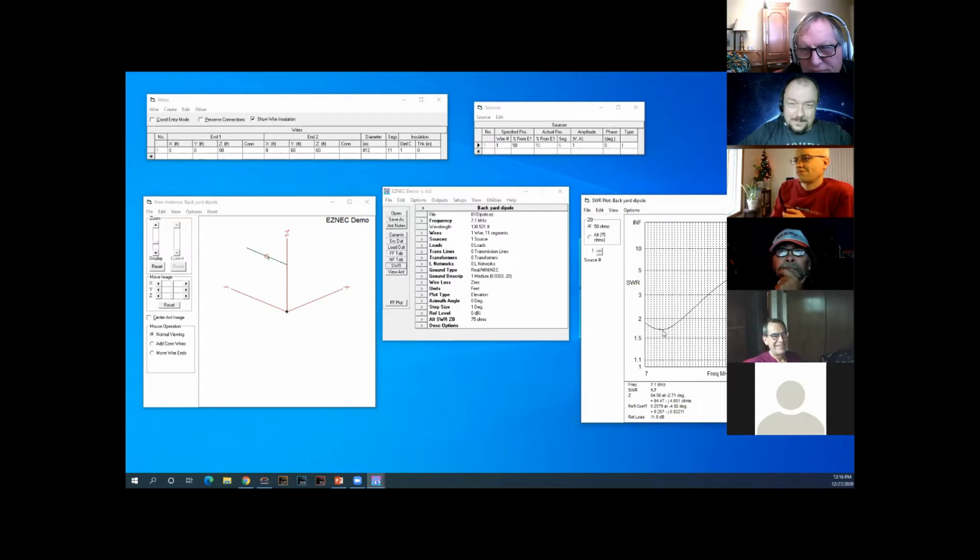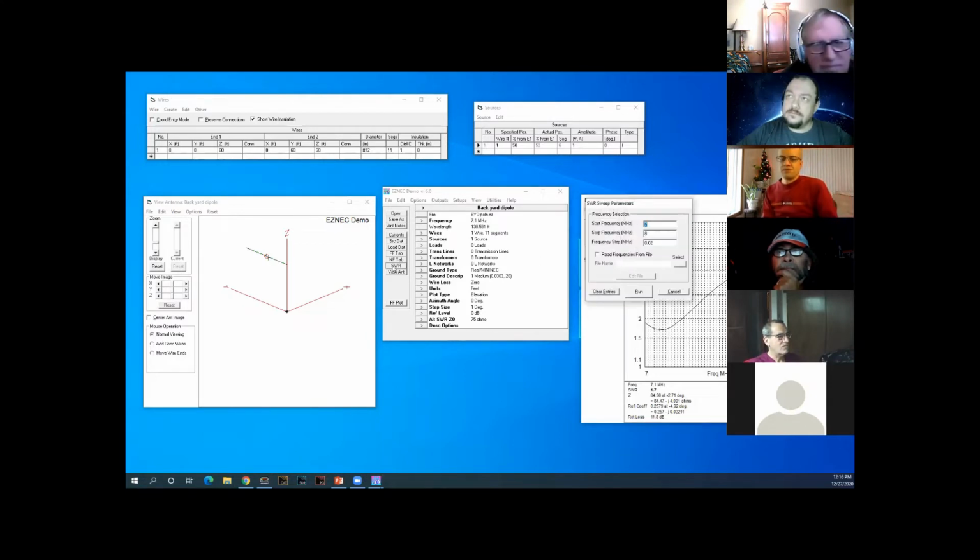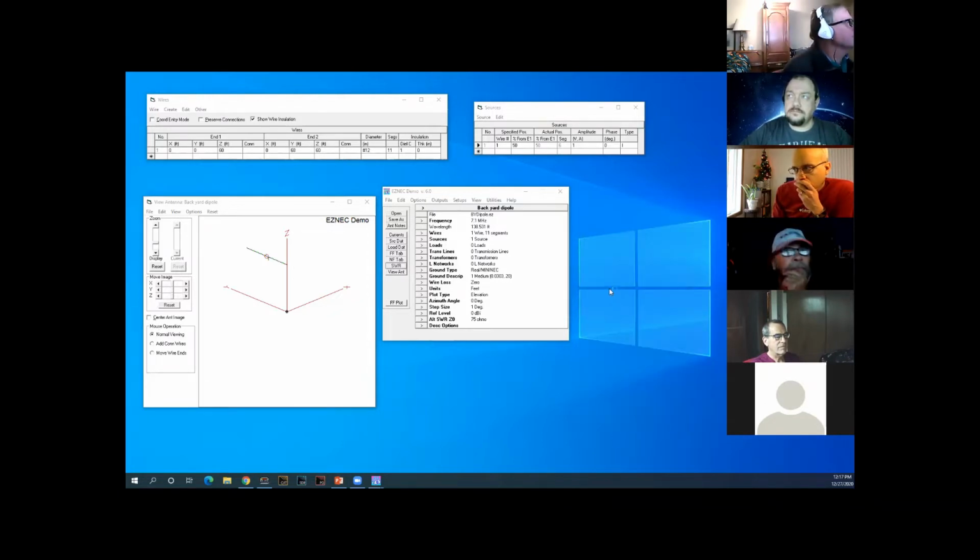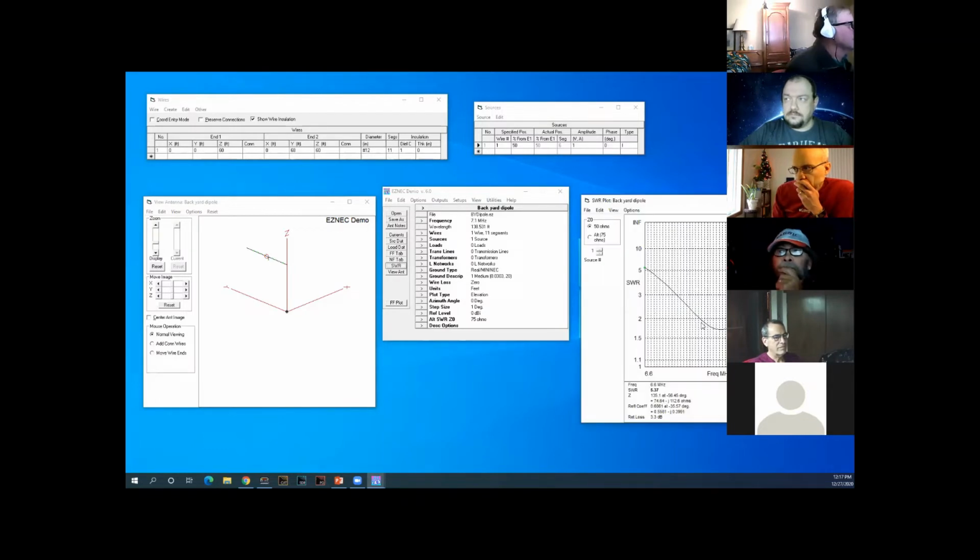Anyway, so we're down here. We want to recenter this. So we have to go into the SWR plot again. And again, this is kind of an iterative process. You have to guess. I happen to know that the right numbers that we want to see are 7.6 and 7.6. So enter those into that field, rerun the SWR plot, and now we have a display that is centered.